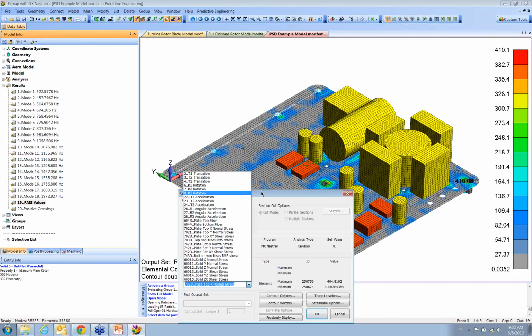When you kick out a number from your PSD, your RMS stress, it's a Gaussian normalized stress value. And in the industry, they always say, no, no, no, we don't want the normalized value because that's only 66% of the time. We want the 3 sigma value. We want the stress value that it will be impossible for this stress value to be higher, 99.73% of the time. That's called the 3 sigma value. And so you take your RMS value, you multiply it by 3. So you get an idea of the uncertainty of the analysis work. It's a bit of a pun.